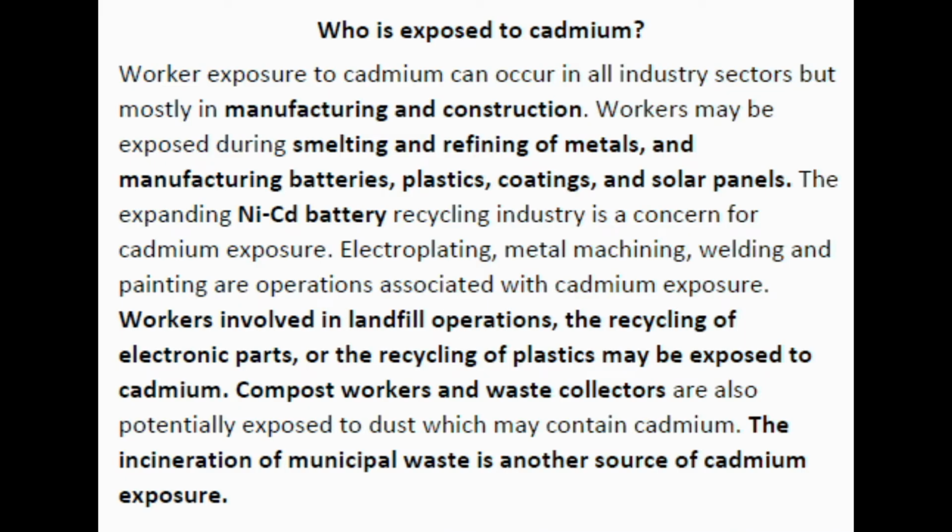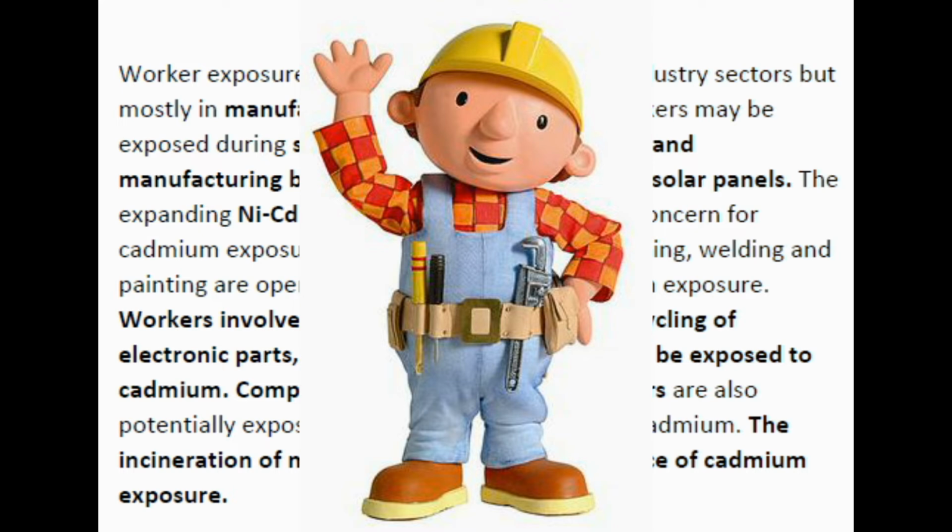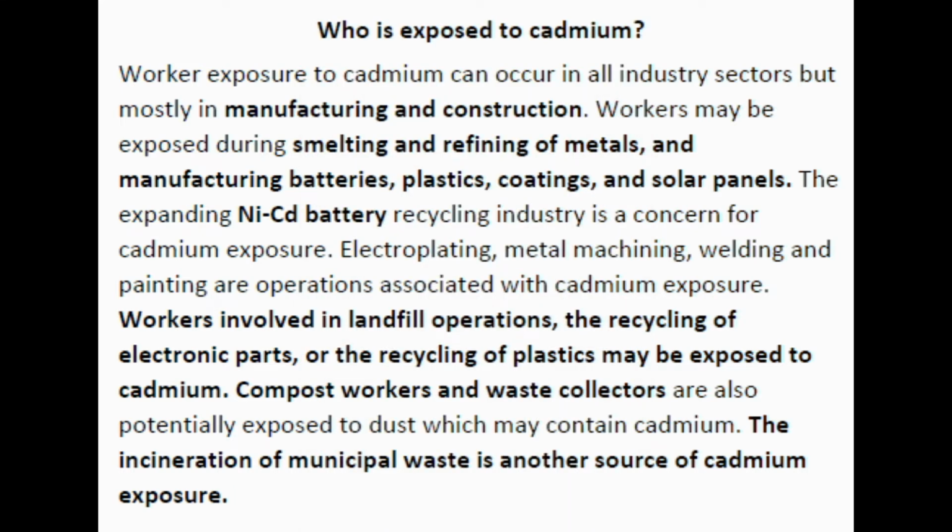Worker exposure to cadmium can occur in all industry sectors, but mostly in manufacturing and construction. Workers may be exposed during smelting and refining of metals and manufacturing batteries, plastics, coatings, and solar panels. The expanding NiCad battery recycling industry is a concern for cadmium exposure. Electroplating, metal machining, welding, and painting are operations associated with cadmium exposure.